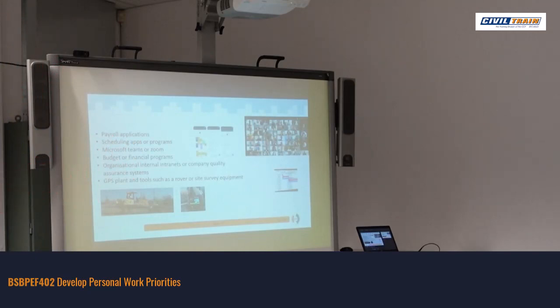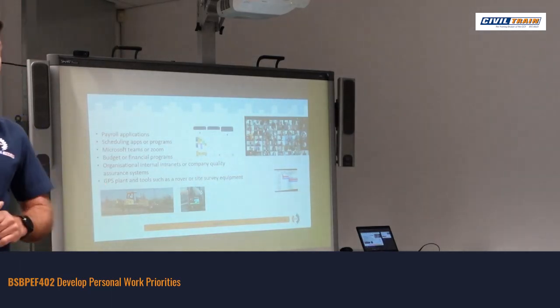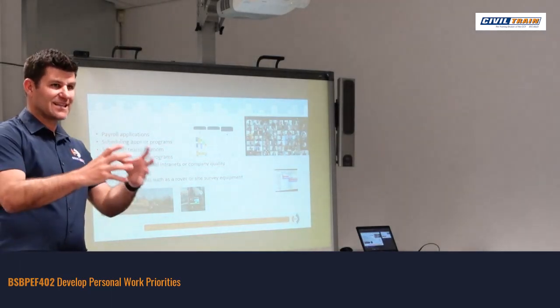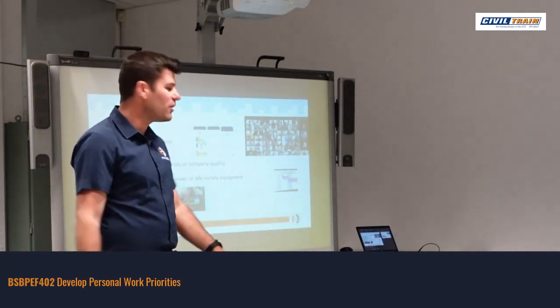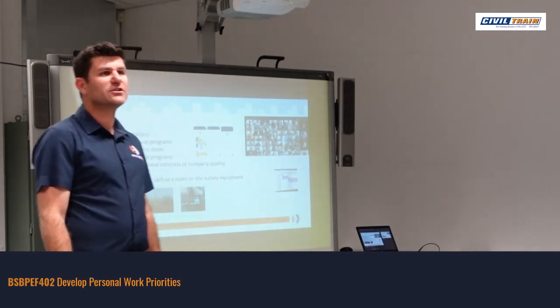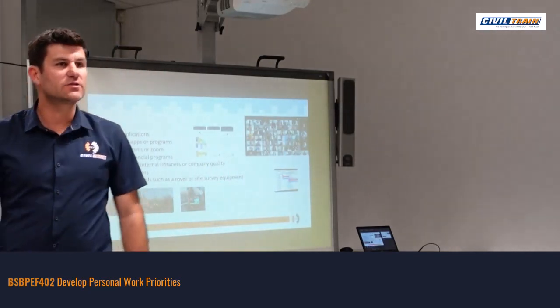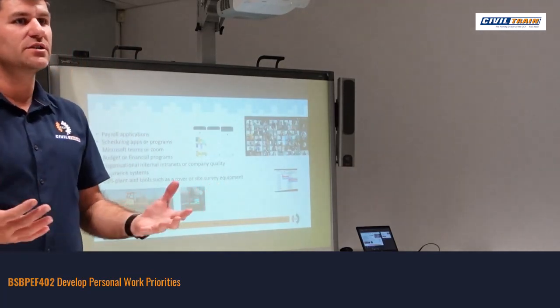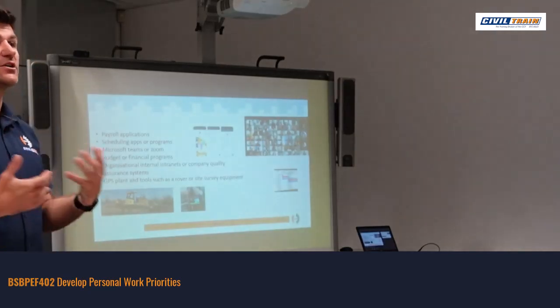Even now as well, I think GPS plant and tools, rovers, and site survey equipment have become the norm. We still train and teach automatic levels and dumpy levels, as far as our training goes, but we know that the industry has pretty much moved away from that. There are even total stations now that can be utilised, which are so simple that you don't need to be a surveyor to use that system.